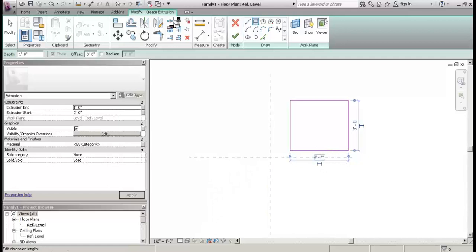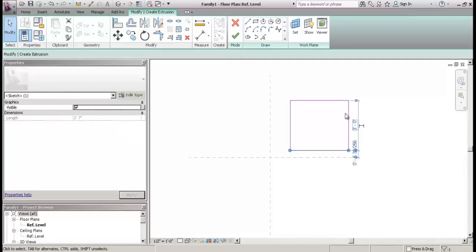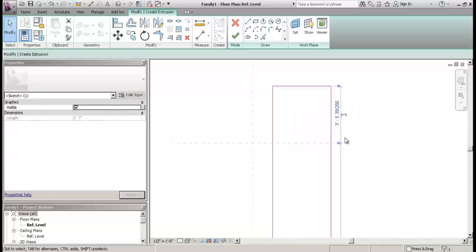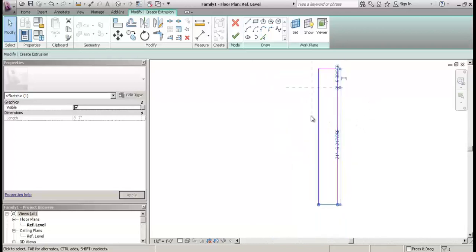Another thing I can do as well, you notice I entered into the extrusion family here. So if I wanted to edit the dimensions of this object, so I want to make this line longer, right? I'm going to select its opposite because it's queuing the endpoints as their dimensions. So I'll say I want it to be 25 feet, right? And if I want to make the other one longer, I'm going to click on that dimension, make that 25 feet.